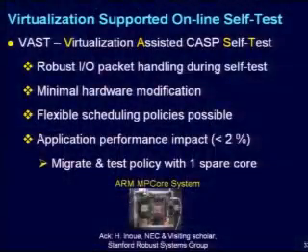Actually, once you have this kind of an idea of online self-test, you can make use of virtualization to optimize your online self-test. The reason is the following: if you wanted to implement the whole thing in hardware, you will run into a problem. Let's say one of the cores is being tested. While it is being tested, the rest of the cores are running, and they may be generating requests for this core which is under test. Now you will need buffers to store these requests, and you would not know how many buffers you would need.